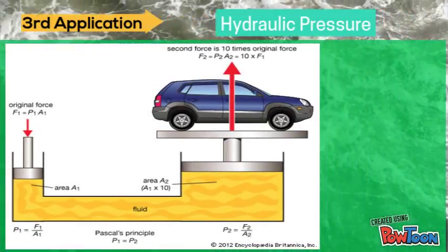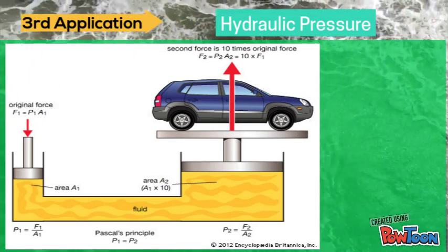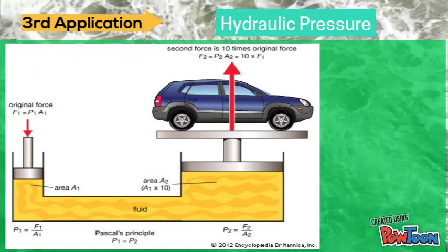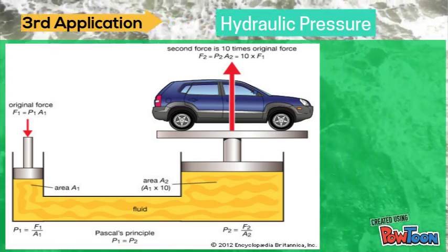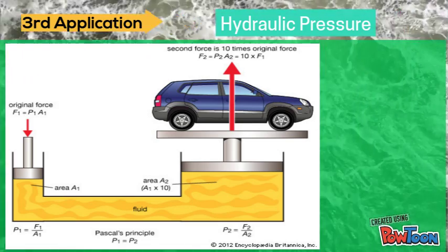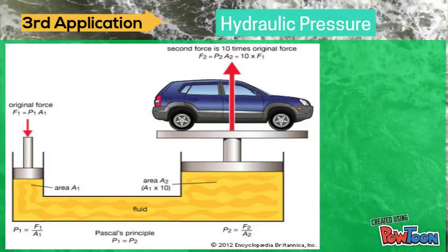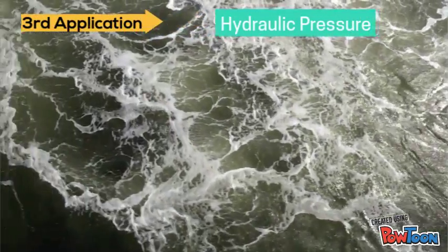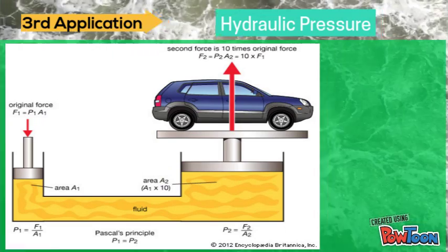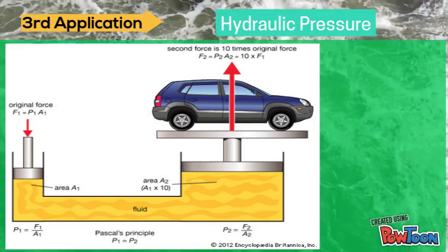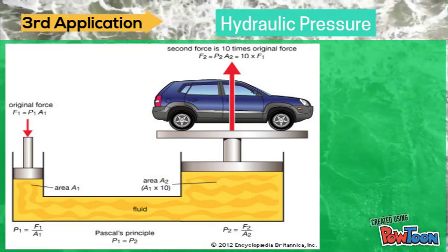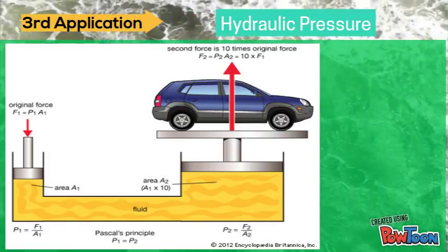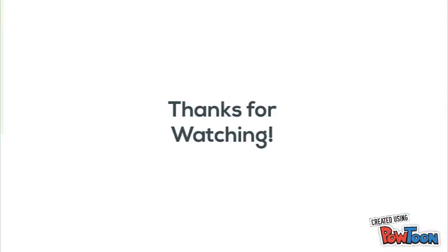Beneath the floor of the shop is a chamber containing a quantity of fluid, and at either end of the chamber are 2 large cylinders side by side. Each cylinder holds a piston, and valves control flow between the 2 cylinders through the channel of fluid that connects them. In accordance with Pascal's principle, when one applies force by pressing the piston in one cylinder, which is the input cylinder, this yields a uniform pressure that causes output in the second cylinder, pushing up a piston that raises the car.